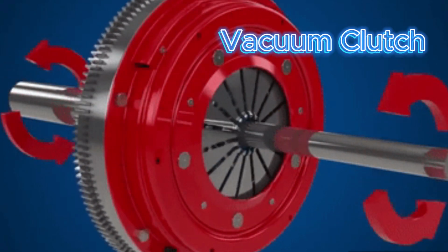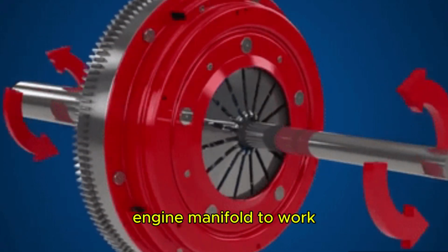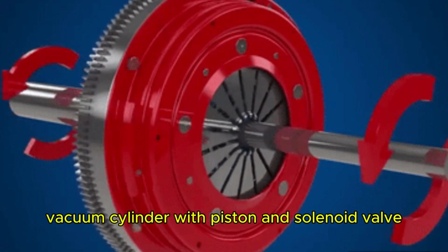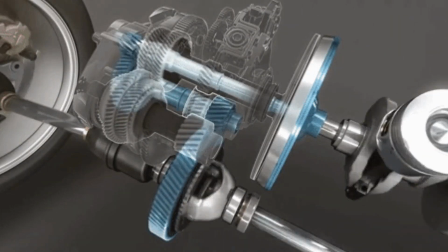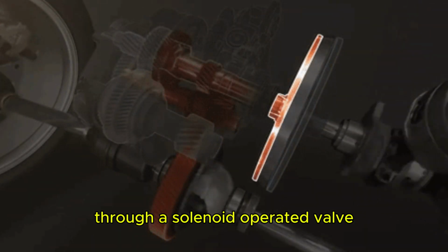Vacuum clutch. This clutch uses the existing vacuum in the engine manifold to work. The vacuum clutch consists of a reservoir, non-return valve, vacuum cylinder with piston, and solenoid valve. The reservoir is connected to the inlet manifold through a non-return valve. A vacuum cylinder is connected to a reservoir through a solenoid-operated valve.